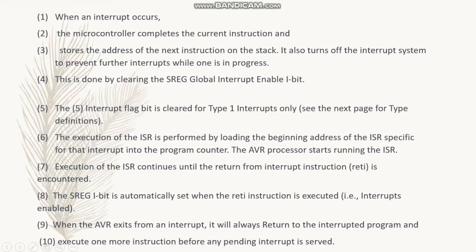instruction RETI is encountered. The SREG I bit is automatically set when the RETI instruction is executed. When the AVR exits from an interrupt, it will always return to the interrupted program and execute one more instruction before any pending interrupt is served.